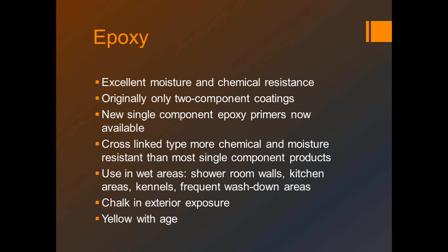And we were talking about breathability with acrylic finishes. Well, epoxies are a vapor barrier, and that moisture will build up behind there, and you can get enough hydrostatic pressure behind there to actually pop it off the floor. We really do need to kind of move on today, but I think that is an excellent idea for a session sometime in the new year, is to talk about resinous flooring systems. So we'll put that on our to-do list.